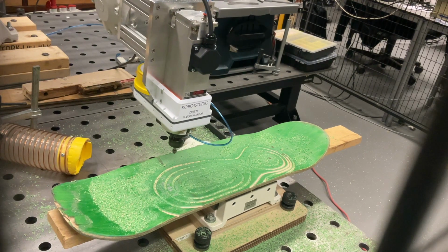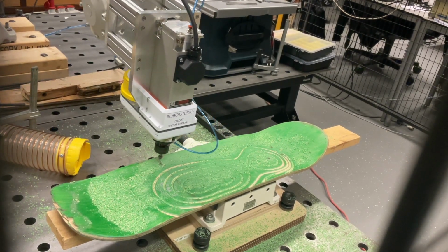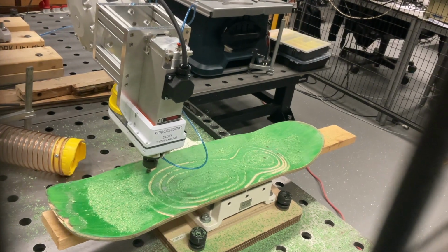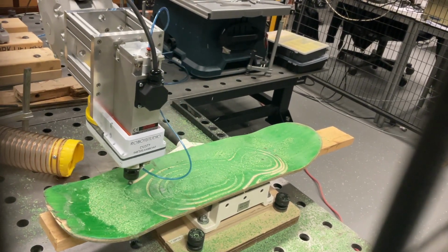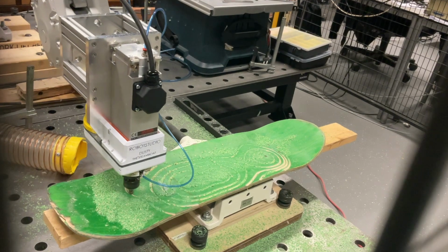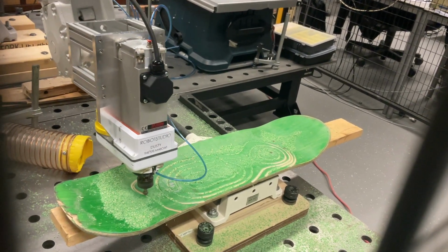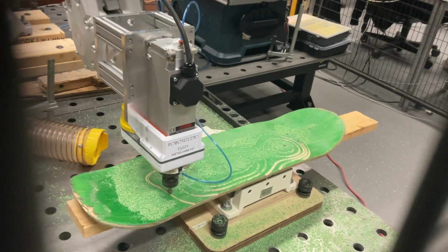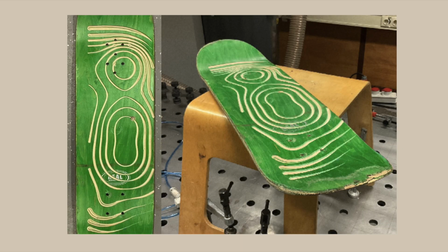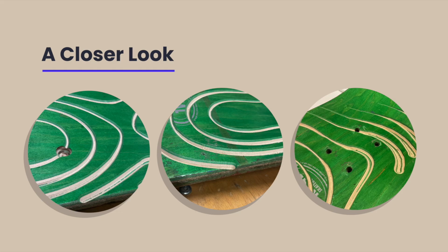The first milling on a cloud test to be carried out was on the skateboard deck. The surface which was processed was covered in grip tape right before the processing occurred. When the grip tape was removed, a large plywood surface with little to no surface wear was exposed. The process's results, though not perfect, showed smooth milling lines, creating an enormous contrast due to the plies on the skateboard construction being colored differently.